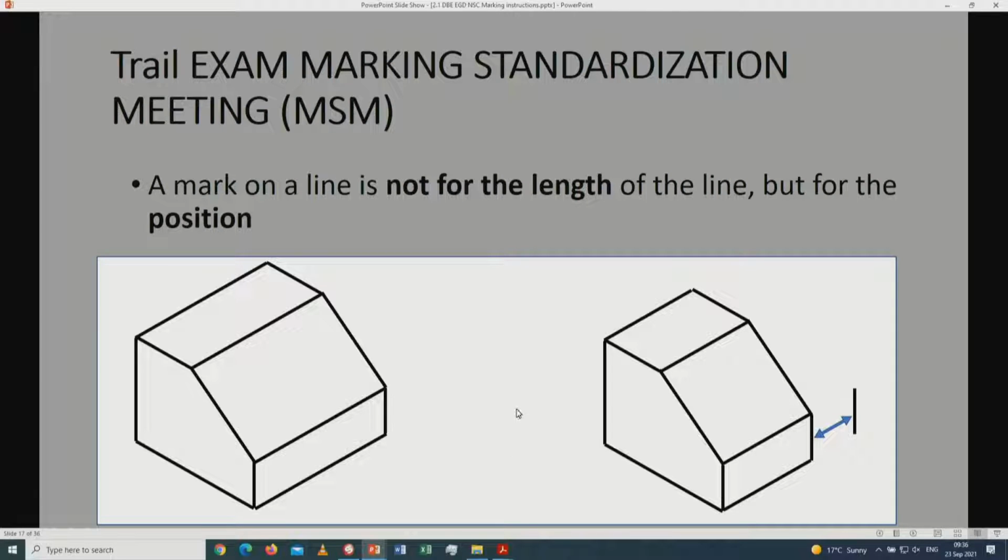Over here, I want to point out, I also showed it in paper 1. What you see over here is the correct answer. So the distance from that point towards that point is what it's supposed to be. You've made your transparency, and now the learner has got this point shorter towards this position. It doesn't mean that the isometric drawing is wrong, because the learner still shows some competency in that this line and that line should be parallel with each other, and this line and that line should be parallel with each other.